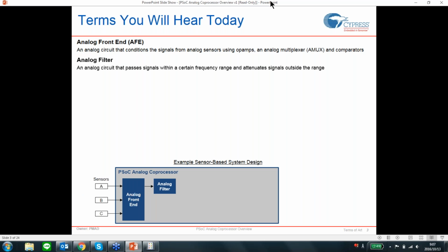Say for example, a low pass analog filter takes a whole range of analog signal at the input and passes at the output only the signal lower than a particular frequency. So if I configure a low pass analog filter for a 4 kilohertz cutoff frequency, it is going to pass the analog signal at the output whose frequency is lower than 4 kilohertz. And we can have low pass filter, band pass filter, high pass filter, notch filter. All those types of filters do fall under this category.